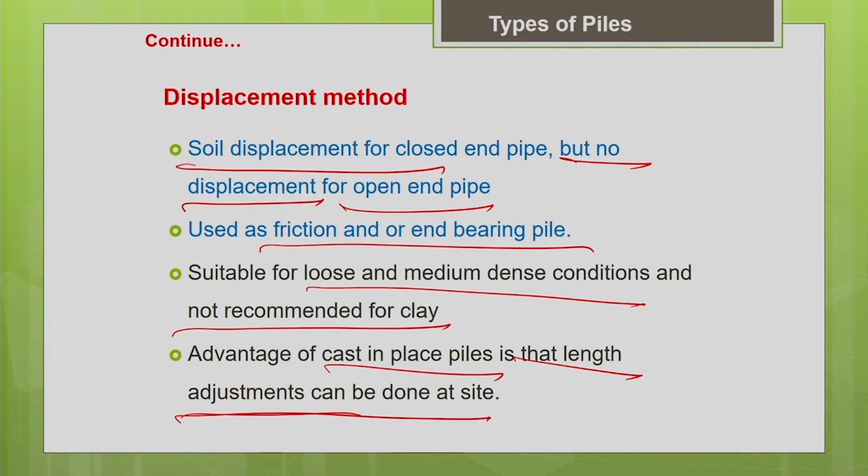You have to go for either cutting or splicing, and that is very difficult with concrete piles. That is why when you go for precast piles, we have to accurately determine the length of the pile needed. So, that is why we need to do a thorough prior investigation. You have to carry out the pile testing program.